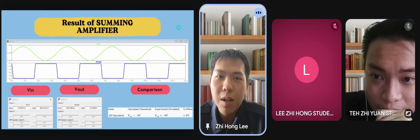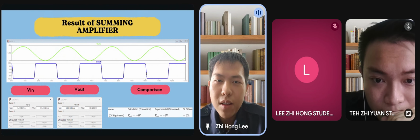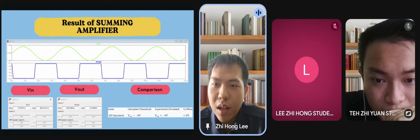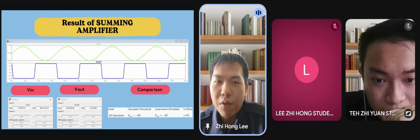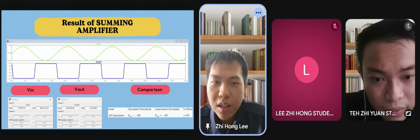Okay, now I will explain the result of the summing amplifier. Our final circuit is the summing amplifier, and we calculated the weighted sum output of -6 V peak, which the simulation closely verified. This confirmed the core principle of weighted algebraic summation.